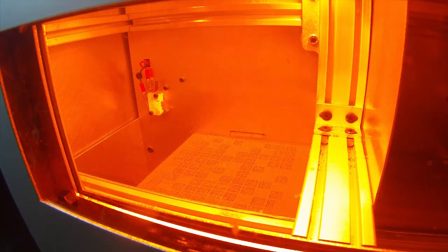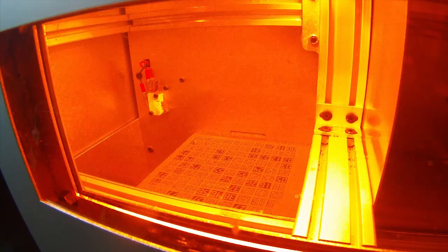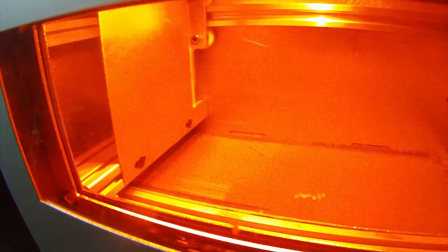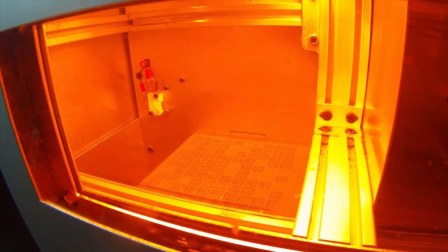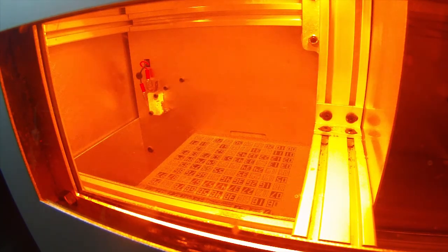Numbers 8 and 9 and 19 had curling issues, and what it would do is cause a plowing issue, which I've been calling plowing. Basically, it curls so tall that the applicator fin will catch, and it will drag that element and plow anything to the left of it off into the overflow bin. If you're lucky, it'll go into the overflow bin. I've also had it catch and then stick and then go back into the right side of the bin, and then it's effectively totally shot.